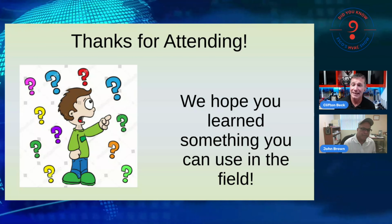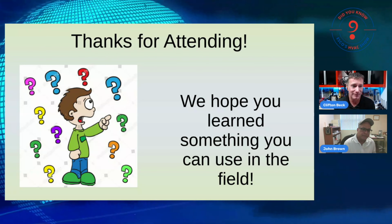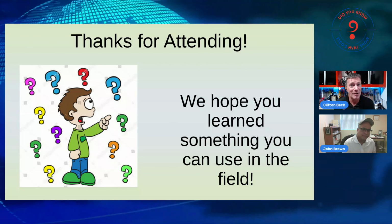If we look at a telephone repair technician 30 years ago working on the same RS-485 platform, his most important tool was the voltmeter. If we talk to a computer technician working on an Ethernet connection running on an RS-485 platform, what is his most important tool? His meters. Voltmeter. So in our industry, we follow the exact same protocol. We have a 5-volt DC communicating protocol. If we know what the voltages are supposed to be, you will be successful at figuring out why things aren't functioning properly. And that has been the biggest complaint of technicians.